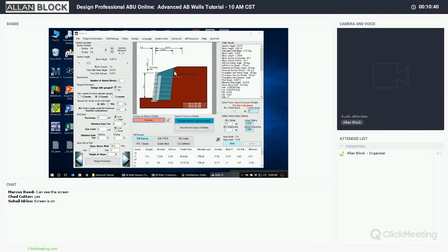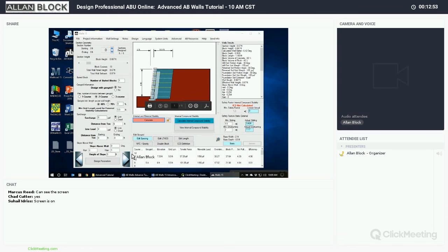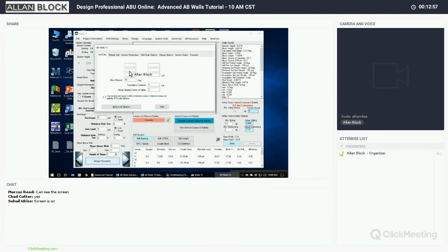So what we did is within the program, we brought in the whole water management section, and that is found in your design parameters. And we're going to kind of live in this little corner over here, because this design parameters, when I click on this, it launches another submenu. And I've got a lot of different options in here, and the big one kind of being this wall drain options. Okay, yeah, I am going to use the default values. I guess I hadn't moved that, so the default soil values are at 30 degrees. So we'll just leave that as yes.